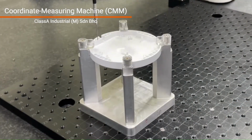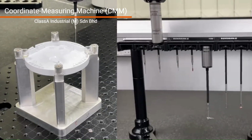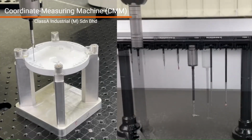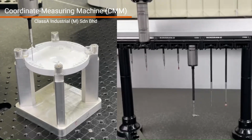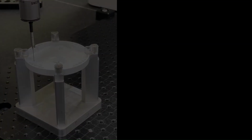SP25M scanning probe with 2 sensors in one: a scanning probe and a touch trigger probe. Rapid and repeatable automatic interchange between modular elements. Compatible with probe extension bars up to 100 millimeters long. Flexible change rack where ports can be easily configured to carry any system element.